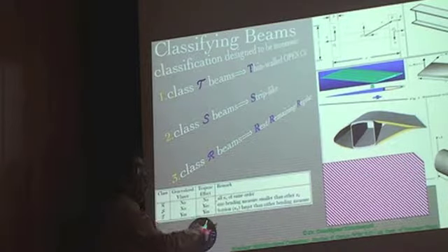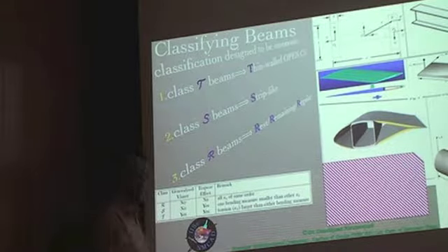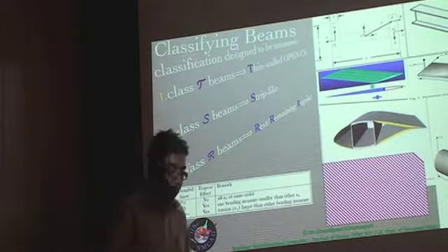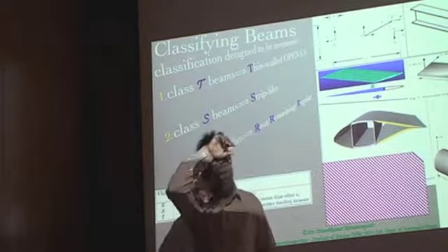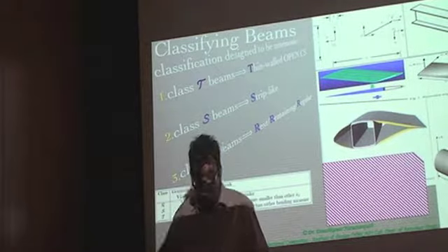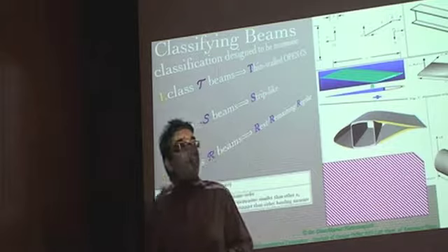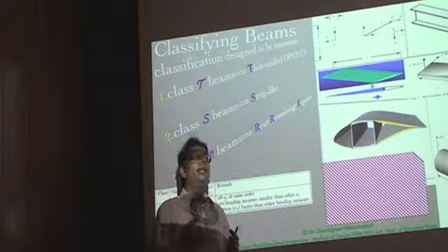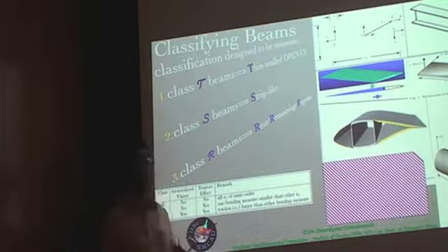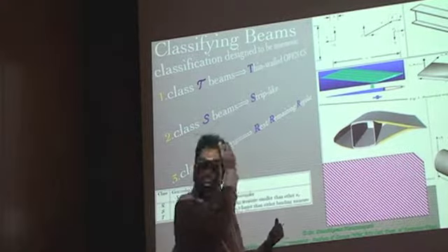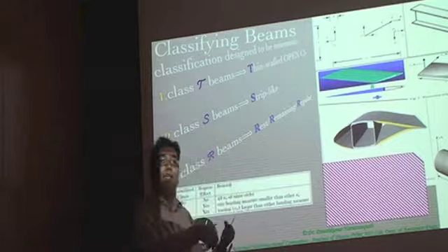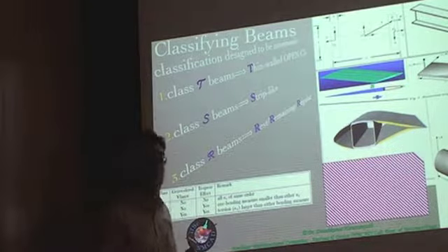Now, in terms of 1D parameters, because these warpings will be solved for by solving certain differential equations, in this case partial differential equations in terms of x2 and x3, when we get those solutions, we can substitute that warping back into the strains and then into the energy, and then integrate it to get the energy per unit length of the beam.